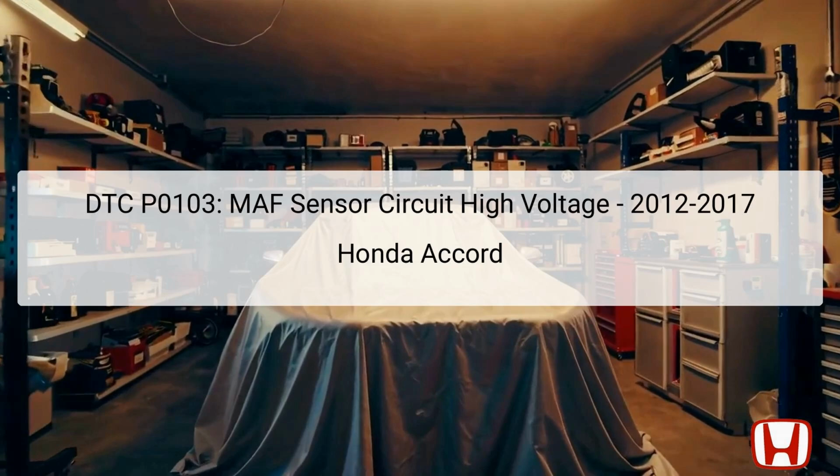DTC P0103 refers to a high voltage issue in the mass airflow (MAF) sensor circuit. This diagnostic trouble code indicates that the voltage signal that the engine control module, ECM, receives from the MAF sensor exceeds expected thresholds, leading to potential fueling and performance issues.